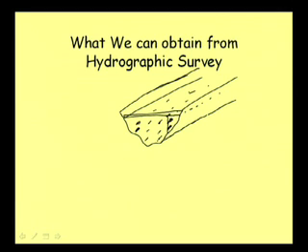That surface velocity we can measure by putting a float on the surface. We put the float and observe what distance it moves in a given time, so that we get the velocities. And then suppose on the surface this is the velocity, at this point some amount of velocity. So, if we plot all those things, we can get the vertical velocity variation in the vertical section.